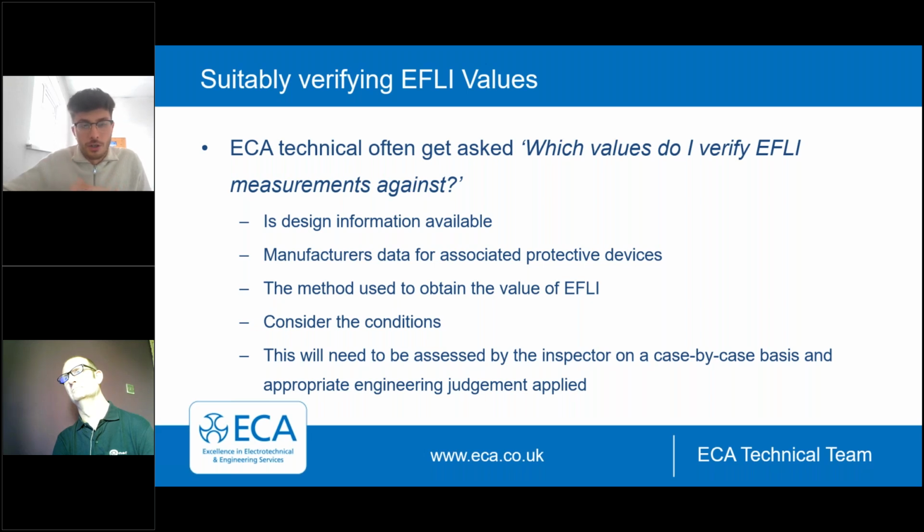Now, if you momentarily shut that piece of equipment down and carry out the test, those conductors are still going to be hot. So you may then be able to compare your readings against the values within BS 7671. There may be other factors affecting your conductors. They may be run through a trunking system that has other live conductors that are also under load. Those are also going to have heating effects on the circuit that you're carrying out your measurement against. So these things need to be considered.